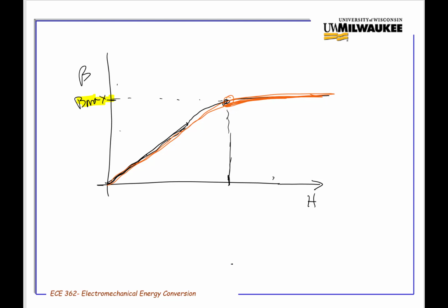Ferro. Which one? What was that? Ferro. Ferro, you're right. Ferromagnetic. That's right, the ferromagnetic material. And if you look at my problem examples I posted, I go into this a little bit. The ferromagnetic material is typically going to be B max. One last point, if you guys can just be a little patient. B max for ferro material, steel, is going to be anywhere from 1.5 to 1.8 Tesla.